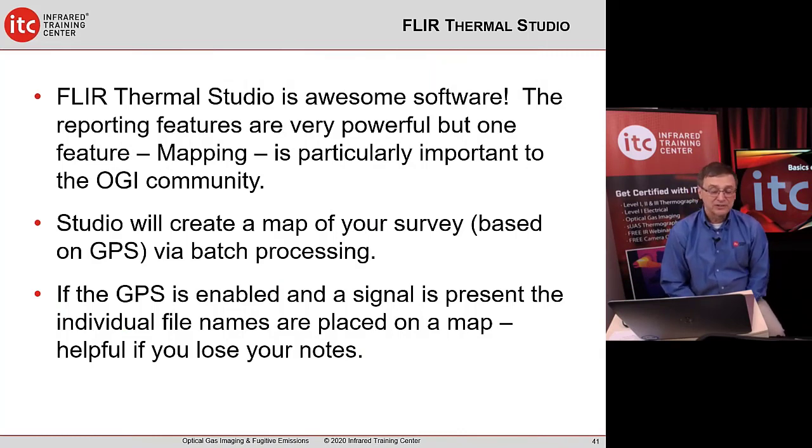And so it'll give you a quantification in multiple units. And also, about a year or so ago, we released Thermal Studio software. And it is awesome. While most folks aren't going to do a lot of temperature analysis in the optical gas imaging world, this has a great feature, mapping. If you have GPS enabled on your camera, and you have a GPS signal, so this doesn't work inside buildings, it won't work in basements, etc. Every time you store an image, it's going to store the GPS signal, and you can batch process those images in there, and it will make a map of where you were.